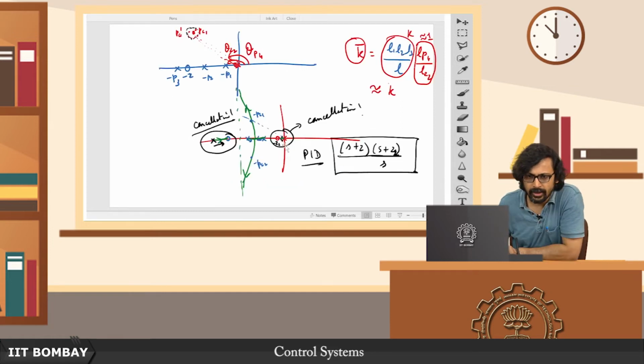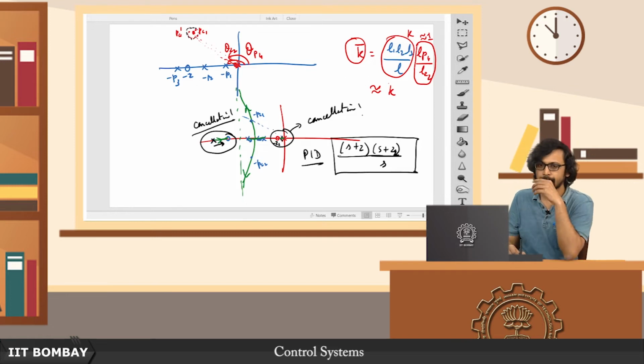So here we have this. Suppose this was the actual PI controller, and we shift just this pole-zero pair a little to the left. What happens? It is clearly evident, because of the continuity of the root locus, that this closed loop pole PC1 is not hampered by much. Maybe the K will change slightly and it will still accommodate for this.